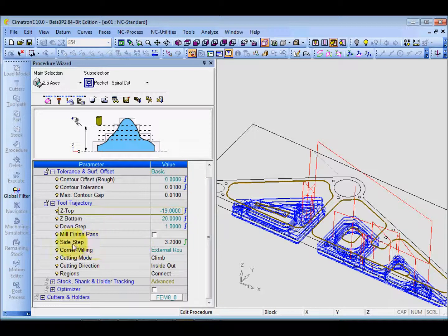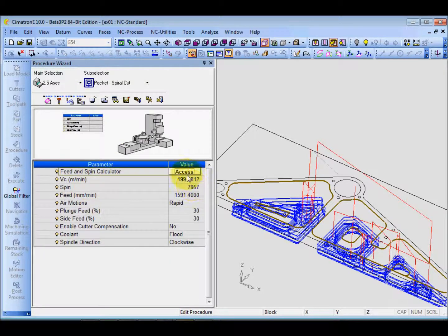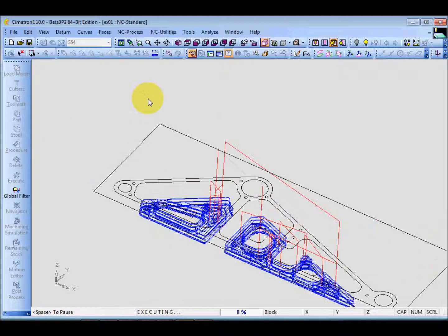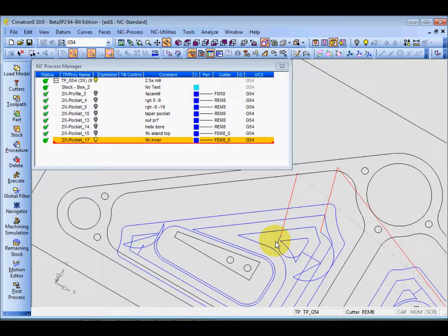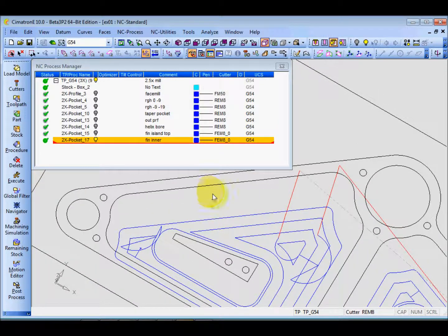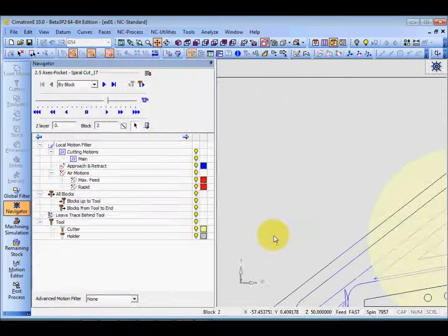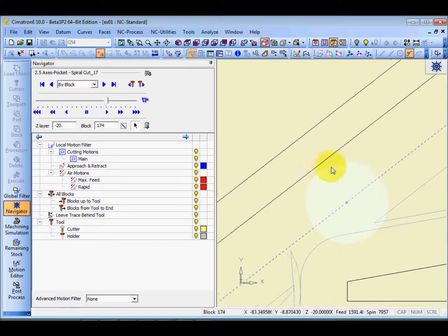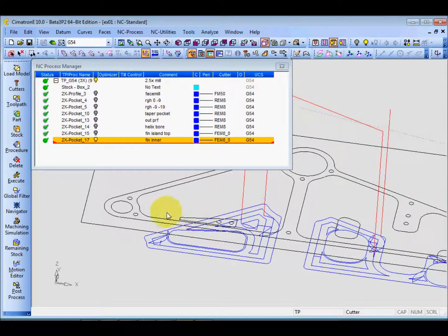And now, how about the rest around and this inside out? Okay, we use it inside out. Next is to adjust RB and feed rate if you need, and execute. And this is the finishing for the bottoms, just for the bottoms, not the side. You can check by going to top, navigate, and you have a gap of 0.5 still, because this is just for the finishing of the bottom.